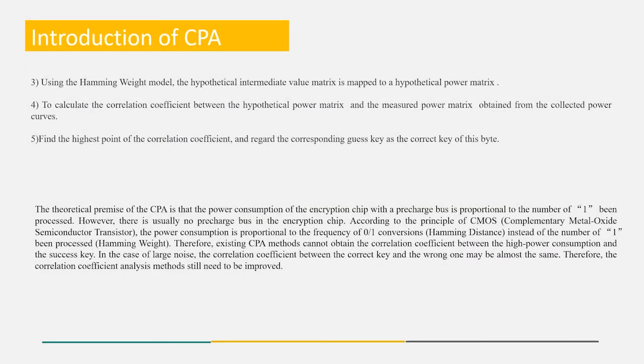In the CPA attack, calculating the correlation coefficient is a very important part, distinguishing it from other side-channel attack methods. The highest correlation coefficient corresponds to the correct key. Otherwise, the intermediate variable and power consumption do not have the expected directly proportional relationship, due to the wrong key.